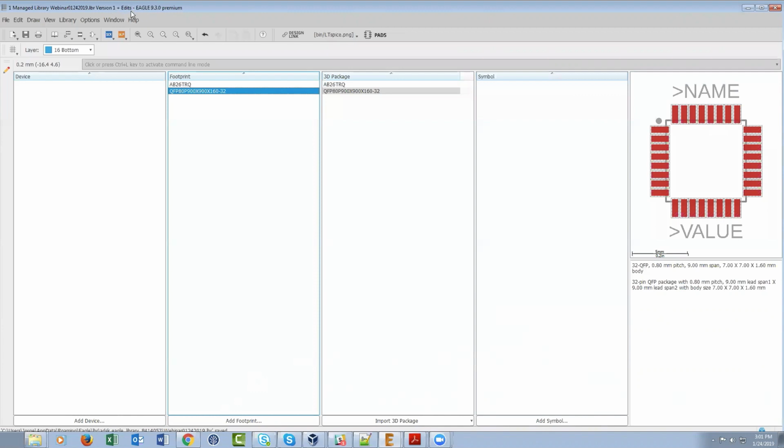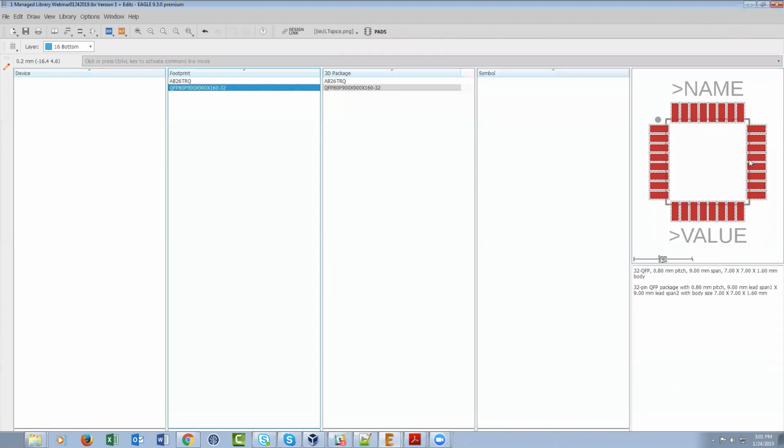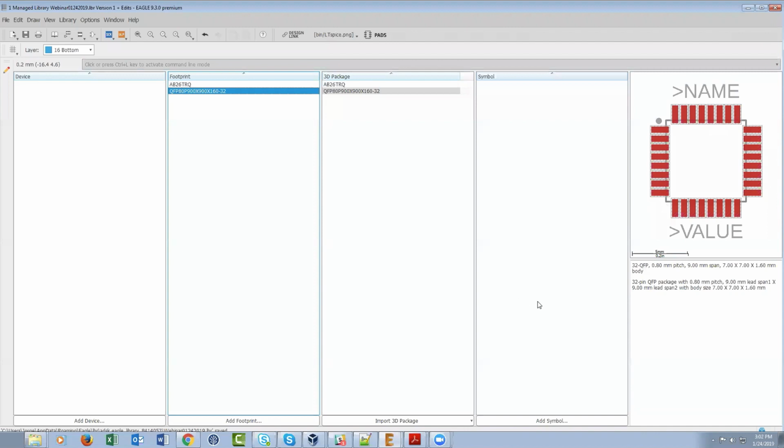If for some reason you don't tend to look up here, you'll notice that the icon at the bottom becomes blue. Right here, this little blue box that says D for draft lets you know that you have some edits in the local version that haven't been pushed to the cloud. We can push them to the cloud just by going Library, Create new version. You'll see we have some other options here. You can discard the local edits, you can update to the latest versions on the cloud, or you can create a new version. We're going to create a new version. We'll say okay, it's creating.